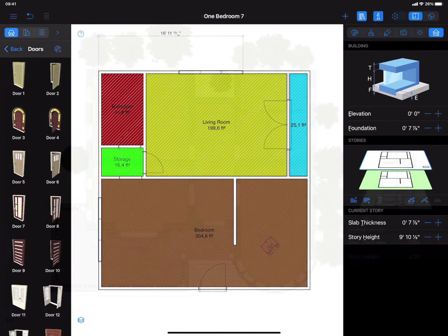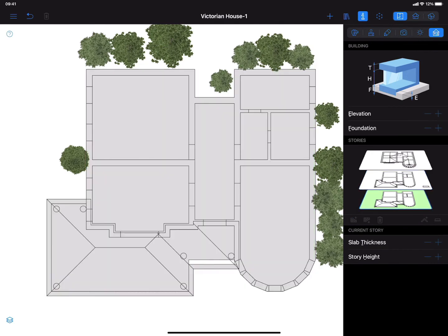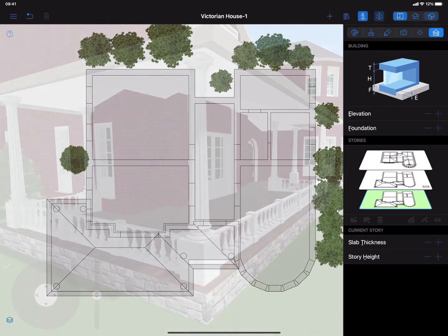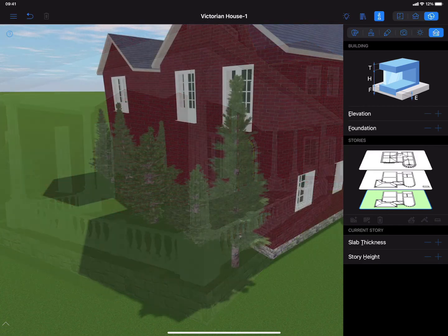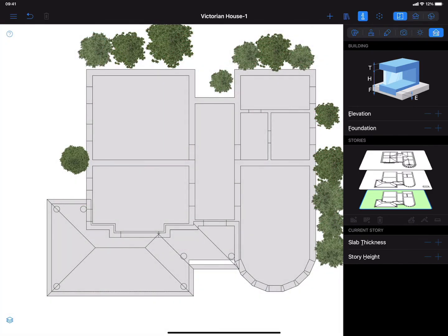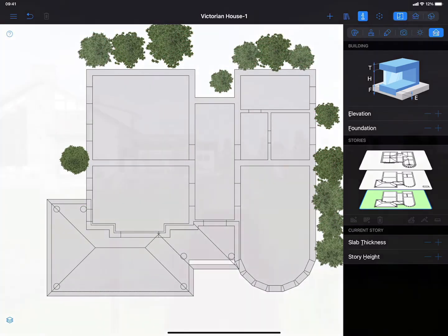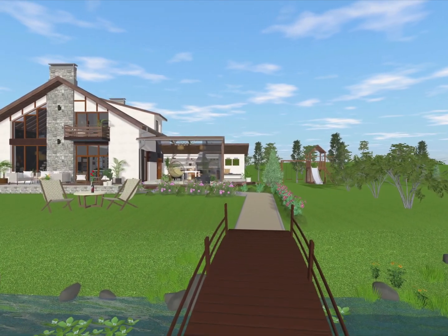trash can button. The site layer accompanies the ground floor layer. They both have the same elevation level and both must be present in any project, but they have different purposes. The ground floor is intended to keep the parts of the building located on the ground level. This can be the ground floor itself, terrace, and so on. The site is used for standalone structures, such as a garden pavilion, pool, fence, or for outdoor plants.